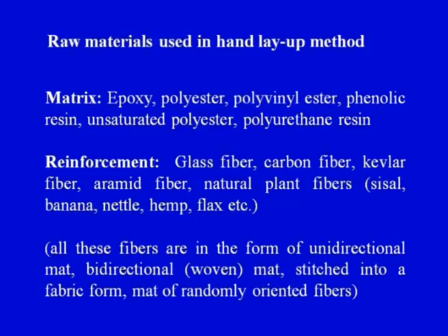We will try to understand it with the help of a diagram also. So, I will read it for you. We have a mold, it can be a flat plate mold as you can see on your screen. In order to make a polymer matrix composite product using a hand layup process, the first and foremost requirement is a mold. So, the mold can be a flat plate mold. We have a diagram in our presentation that we will see of how a flat plate mold would look. So, on your screen you can see that we have a flat plate mold like this.